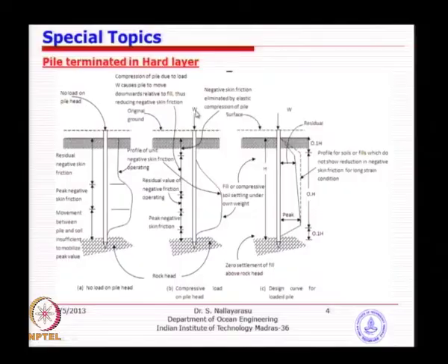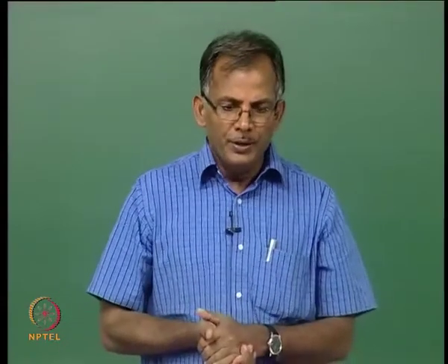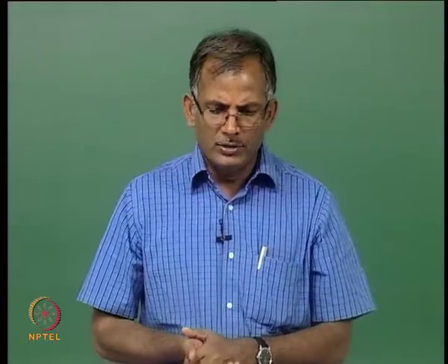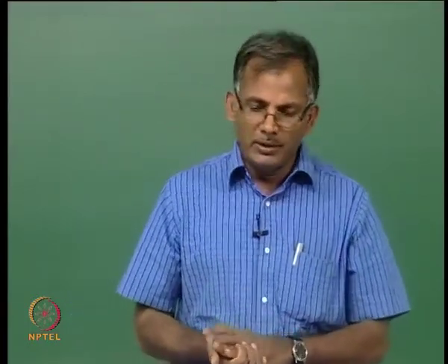You have a pile load coming from your structure, but then the soil in the vicinity is getting added because of the frictional resistance between the pile and the soil, but unfortunately the soil is going down. So this problem is not so much, because we do not actually install in places where soil is filled in offshore conditions. You don't expect it, but this kind of problem is very much there in the onshore as well as coastal areas where you have a fill.